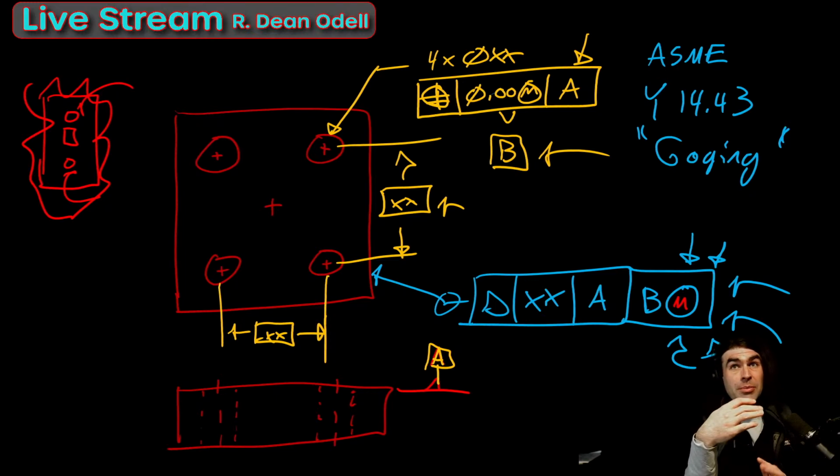Also, CMM software wise, you got to be careful with the fitting algorithm if you're going to be using patterns and features of size at RMB. You kind of have to know what it's doing behind the scenes.